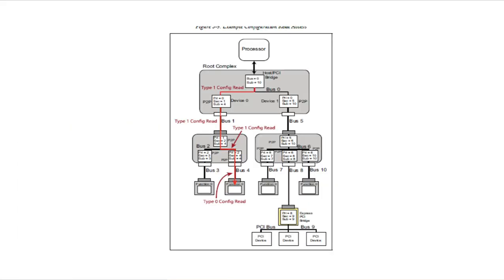Now see, this is the processor. The processor only knows the host bridge, which is connected to bus 0. It doesn't know how many components are connected. The processor will issue an instruction to this host bridge for sending the config packets.